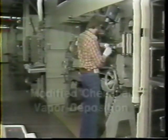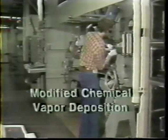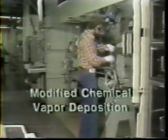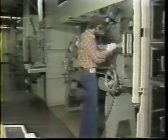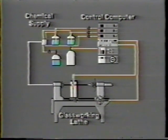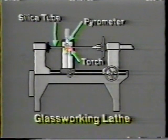Next, AT&T Network Systems uses the Modified Chemical Vapor Deposition, or MCVD process, to deposit layers of glass on the inside wall of the tube. The 3 components of an MCVD system include a glass-working lathe, a chemical delivery system, and a control computer. The lathe supports and rotates the silica tube, while a motor-driven oxygen-hydrogen torch slowly moves along the tube's length.